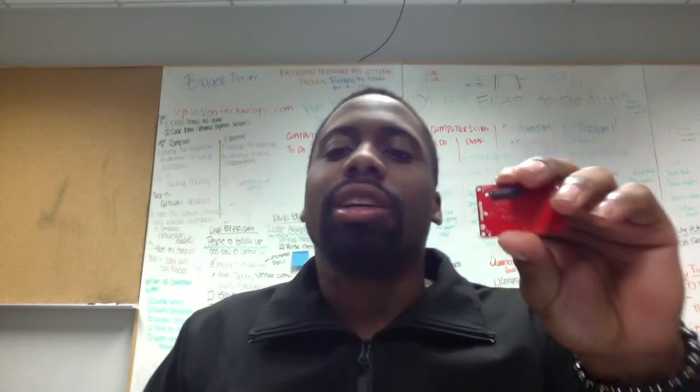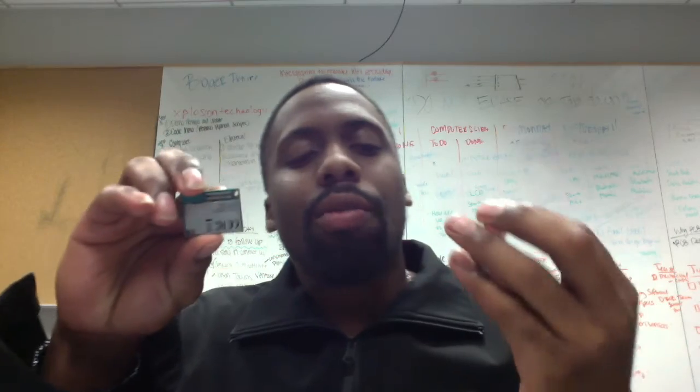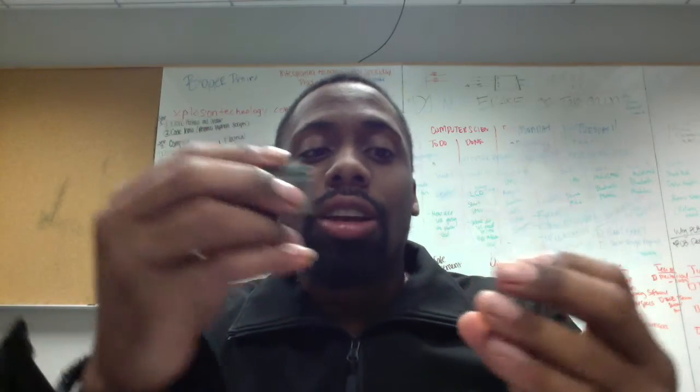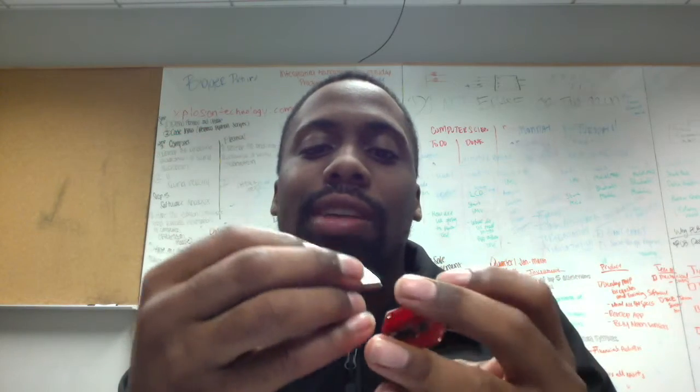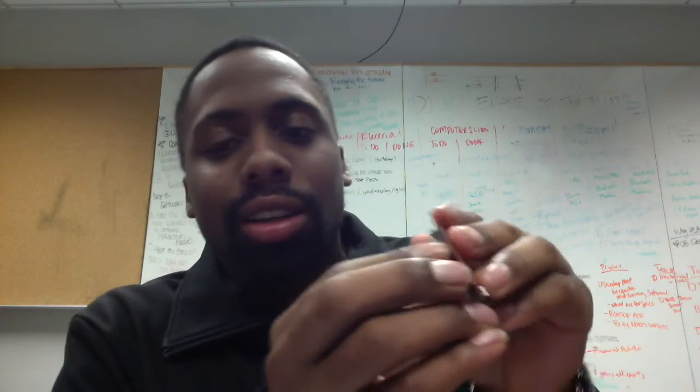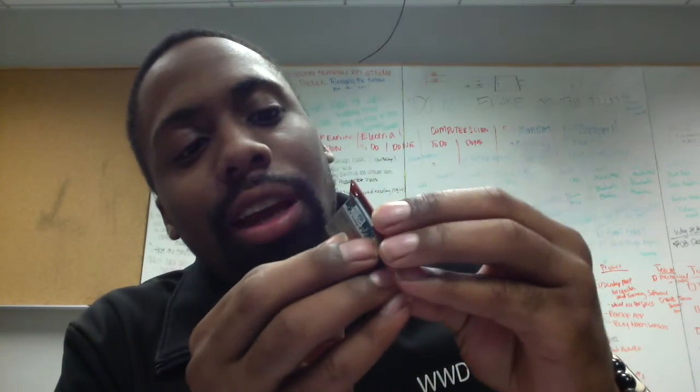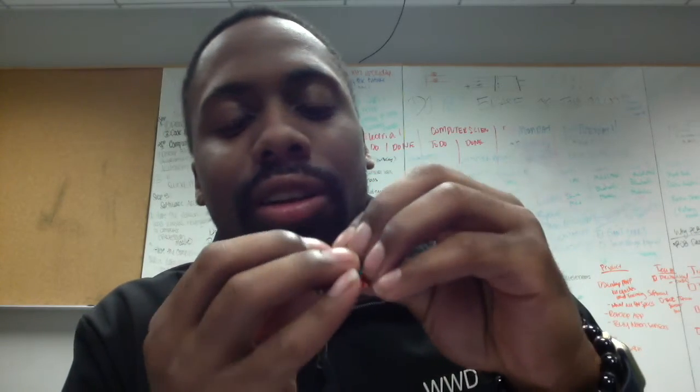So the first thing you want to do is the hardware connection. It's very simple. What we're using here is a console block and the Intel Edison. All you have to do is align the pins to the 70 pin connector, just like this, and you really just snap it together. Literally. Bang. So the first connection is done.